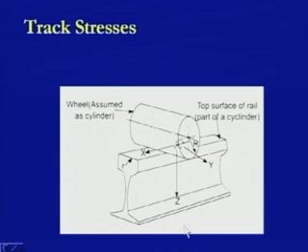So, because of this type of movement, we look at the forces induced in the x direction, that is the longitudinal forces which are caused due to the tractive effort, or due to the braking, or due to the thermal stresses induced in these rail sections because of the fastenings provided at the foot level.